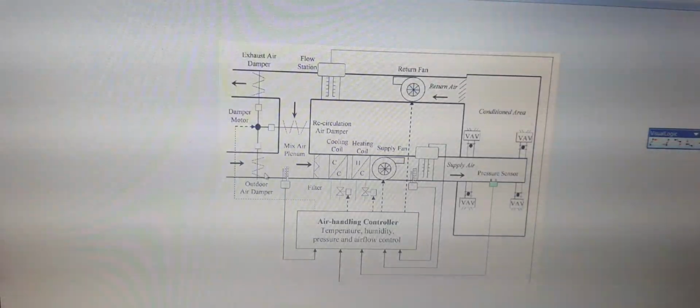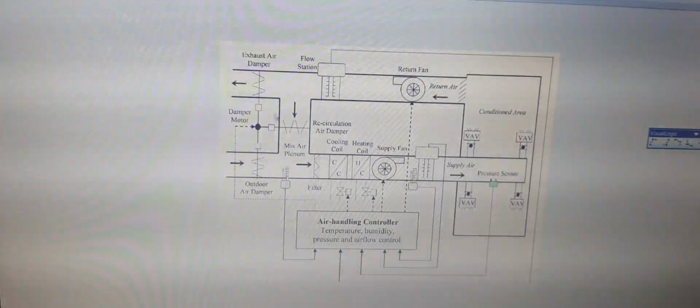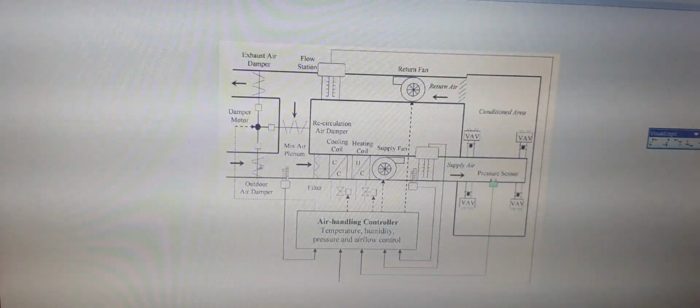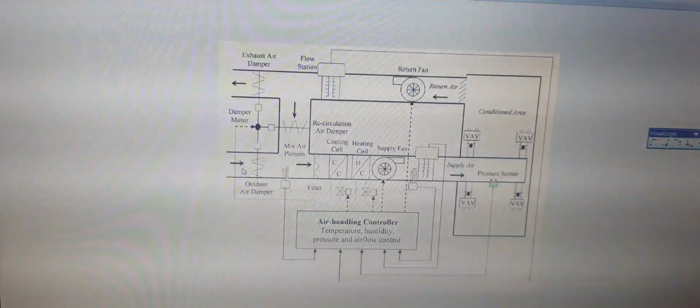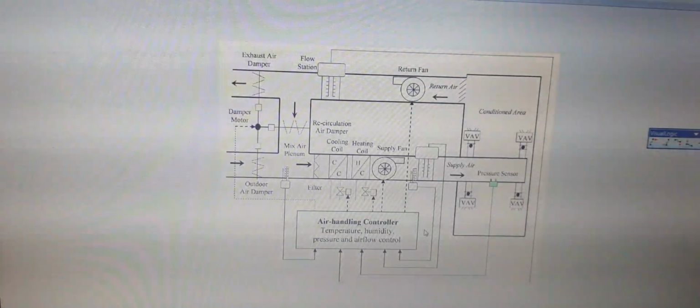Basically, you fully open the outside air damper, you have fresh air introduced. And if you want to have a mixture, 50% fresh air, and you exhaust 50% and you have a mix 50%, because there are 3 actuators, so you have the control option. Also the strategy, you can control the opening and closing of the exhaust, mixed and outer air dampers to have the right amount of mix in the space. So this is a typical air handling unit program seen in Alerton Visio.